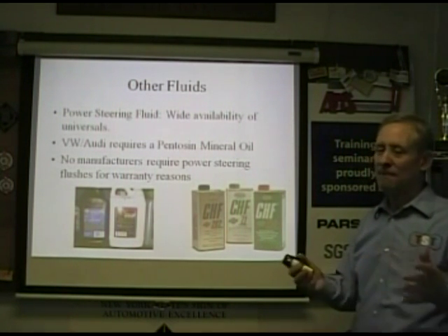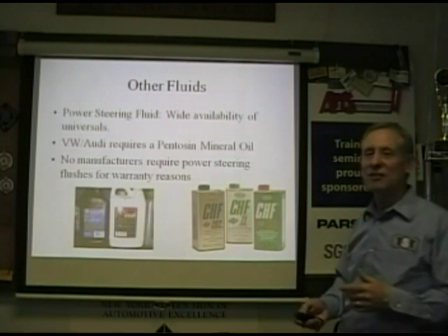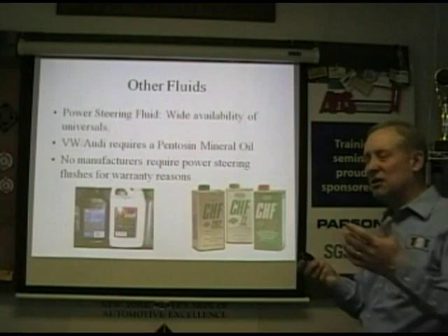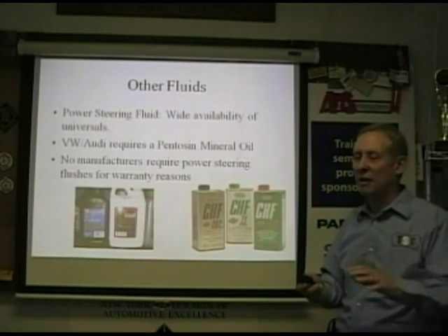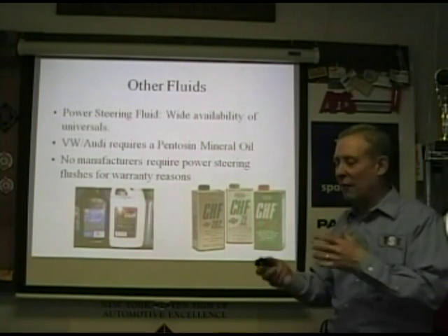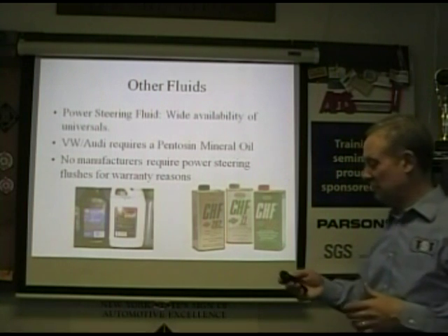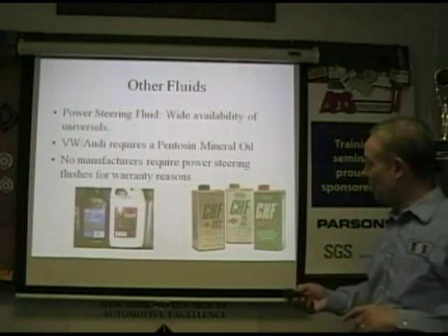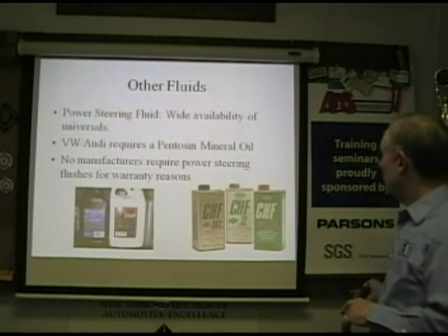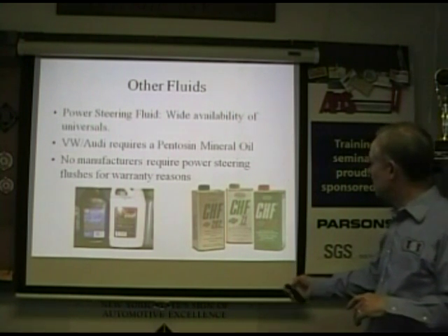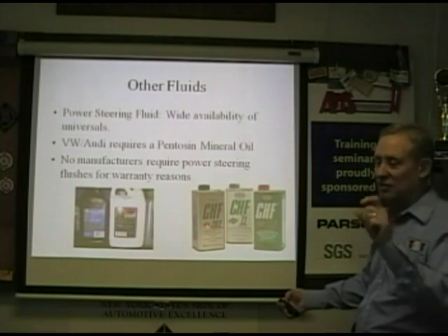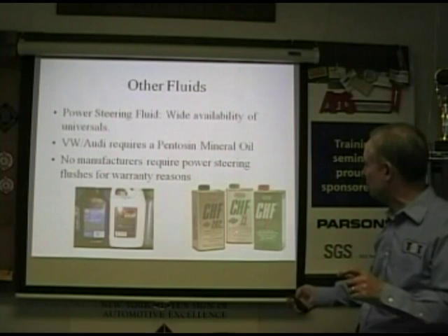Bottom line is, you have to use your own discretion and experience. I usually say 75, 100,000, some high mileage. At some point, you recommend changing the filter, however it's done, and flushing the system and putting maybe a couple of hoses. Certainly, if the thing develops a leak, recommend replacing. Yeah, and flushing it out's not a bad idea. In fact, here's one on the 202s, there's a very narrow window of what it's used in.